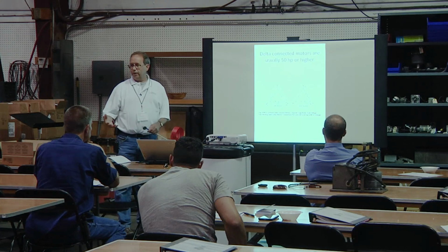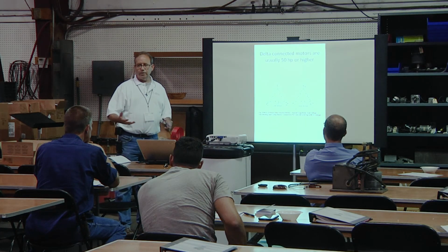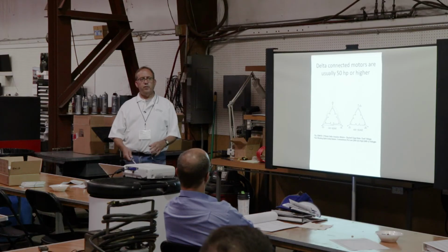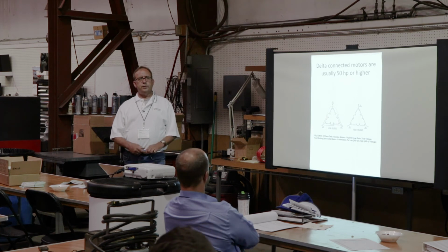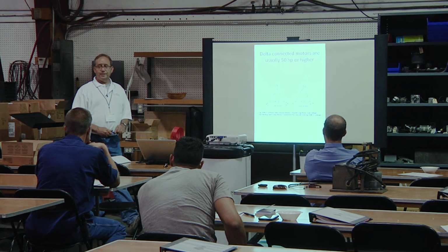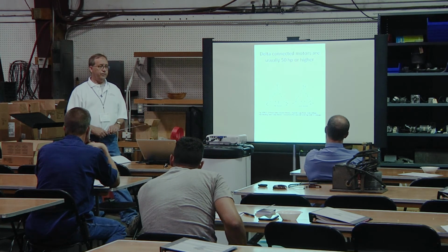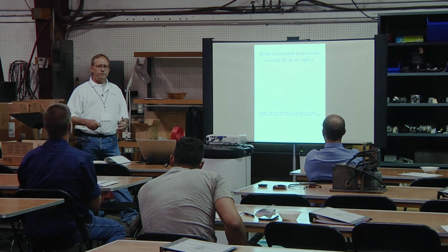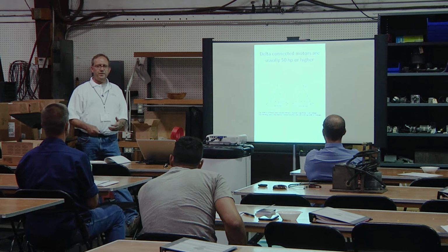A lot of import motors have 12 leads on because they do tri-volt stuff, like 380 volt, or they find compromises with the voltage. You'll see some of them where low voltage is a Y and high voltage is delta. Well, it's not a perfect world. They just find some happy medium, because low voltage is not the same as 277 volts, since you're going to put 230 on it.